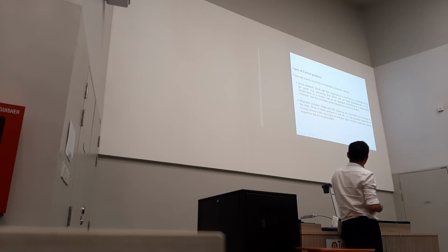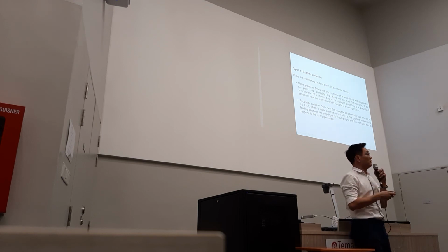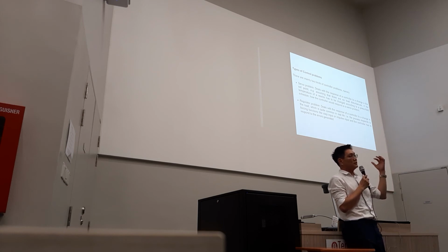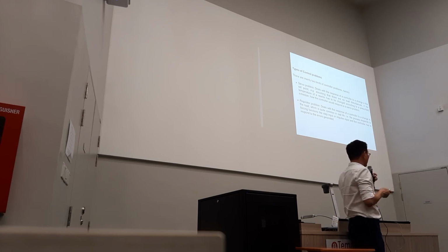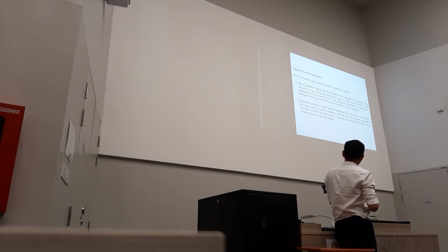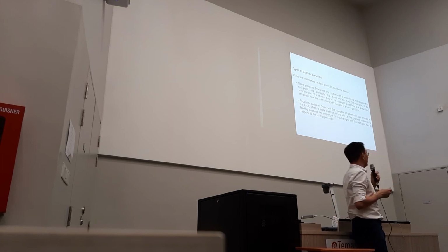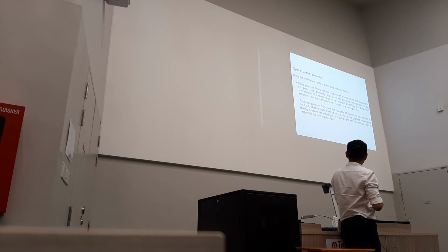The regulator problem is a controller change because of the forcing function. Forcing function means disturbance. So the inlet temperature will change, or the inlet pressure or inlet flow will change. Those kinds of forcing functions disturb my system, and then the controller has to respond to the error generated. It's like I need to regulate the system itself. That controller problem we refer to as the regulator problem.